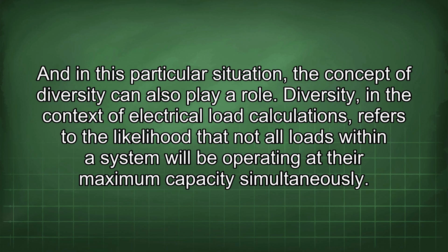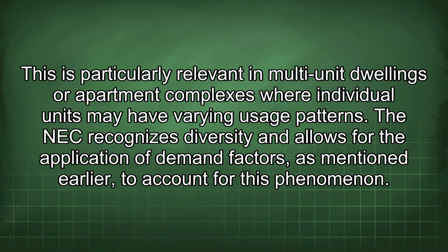And in this particular situation, the concept of diversity can also play a role. Diversity, in the context of electrical load calculations, refers to the likelihood that not all loads within a system will be operating at their maximum capacity simultaneously. This is particularly relevant in multi-unit dwellings or apartment complexes where individual units may have varying usage patterns. The NEC recognizes diversity and allows for the application of demand factors, as mentioned earlier, to account for this phenomenon.